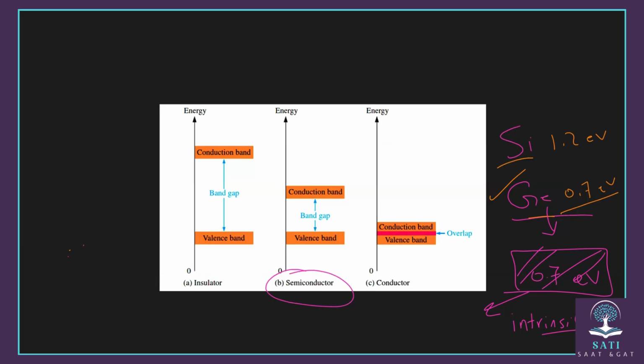Okay, but there is another way to treat semiconductors to make them good conductors, by adding impurities. That means by adding other atoms into these semiconductors. Semiconductors that are made by adding impurities, we call them extrinsic. So you have two types of semiconductors. Intrinsic, which is just by heating them, we increase their conductivity, or the other type, we add impurities to them, and in this case, they increase their conductivity, and we call them extrinsic semiconductors. Okay, how does that happen?